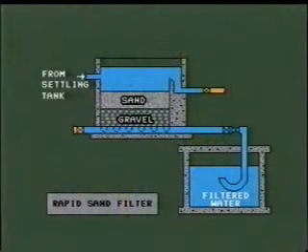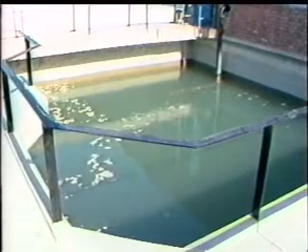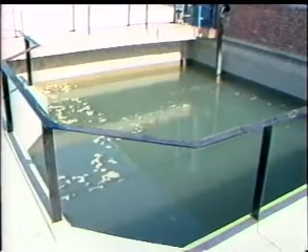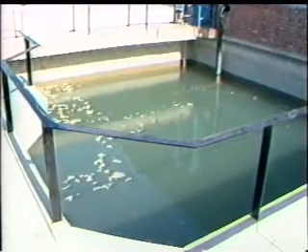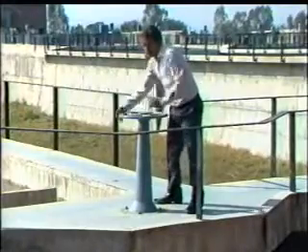During filtration, water passes through beds of fine granular material such as sand, gravel, etc., and gets purified. The filtering media get clogged after 24 to 48 hours in use. It can be cleaned by backwashing.